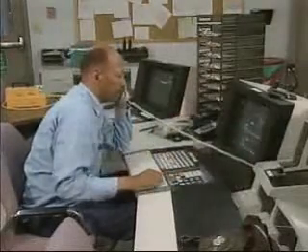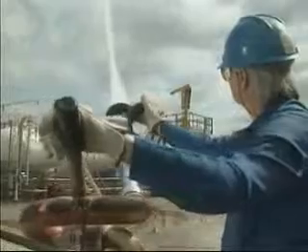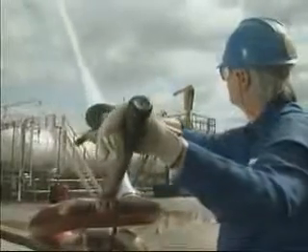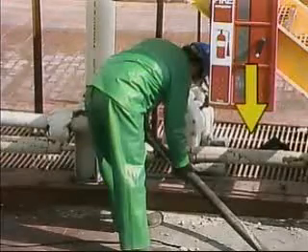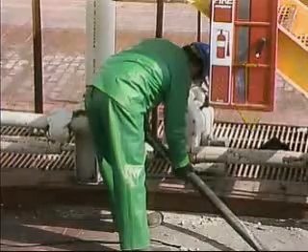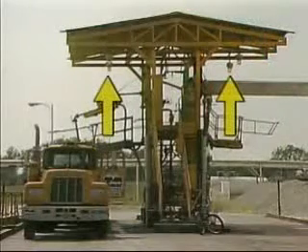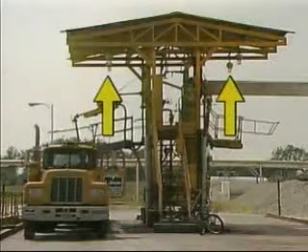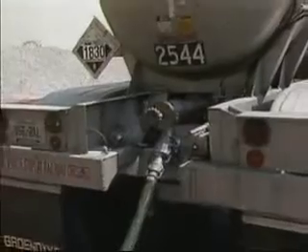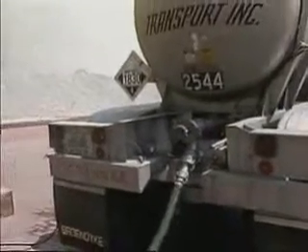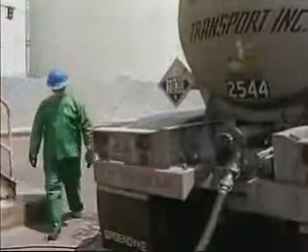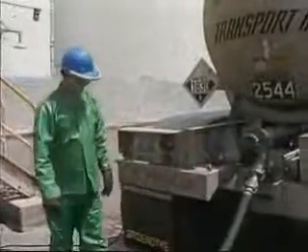These stations are often hooked up with an alarm system to a control room so that immediate help can be obtained in an emergency. Many loading sites also have firefighting equipment, drain pads for collecting runoff from any spills that may occur, and lights, since product transfers sometimes occur at night.